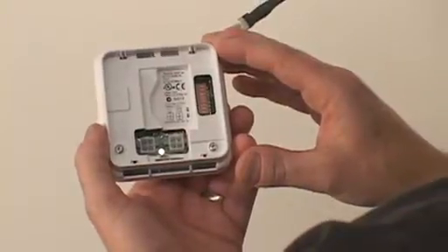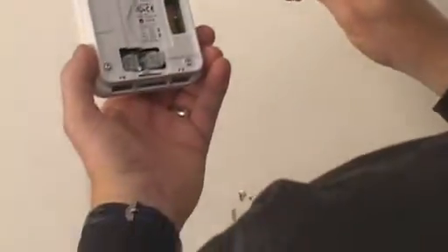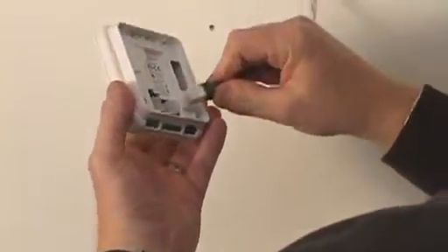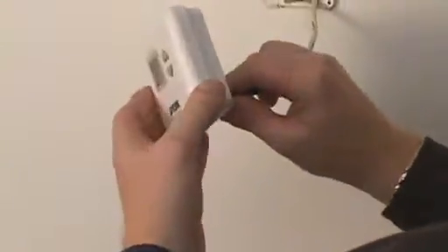Underfloor systems require direct digital control systems, which is really no big deal. And the systems must be commissioned, so it's not quite like turning on a light, but the commissioning is simplified over comparable ducted systems. Experience has shown that plenum integrity is absolutely vital. Attention to holes into the plenum space must be addressed with care.